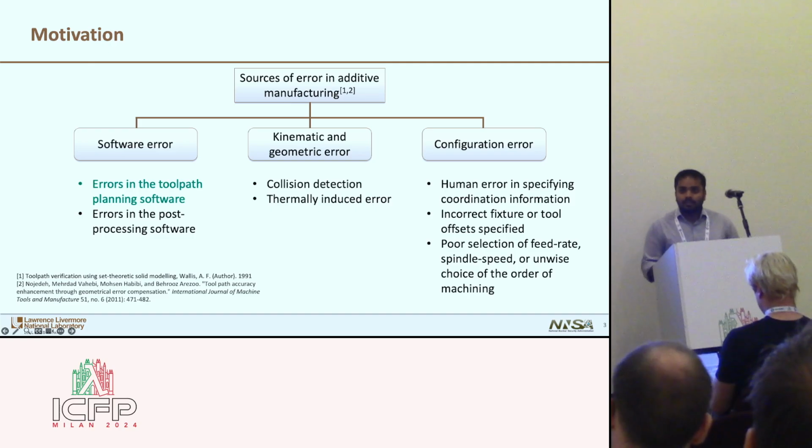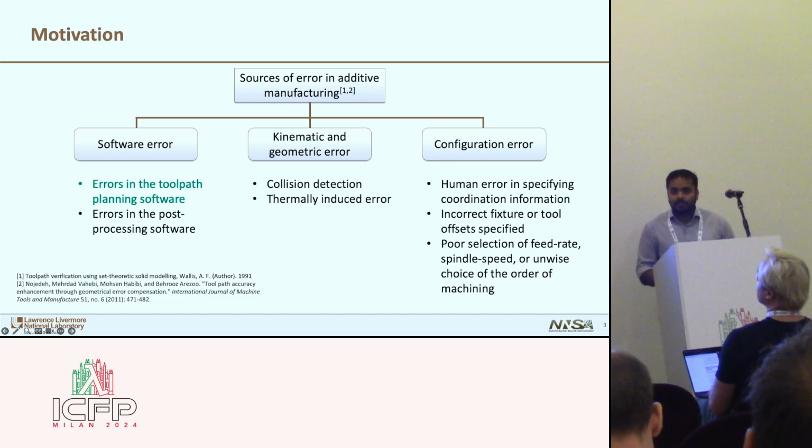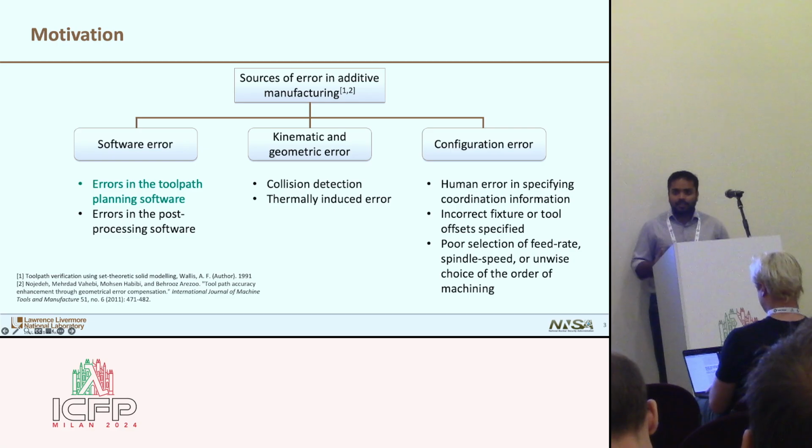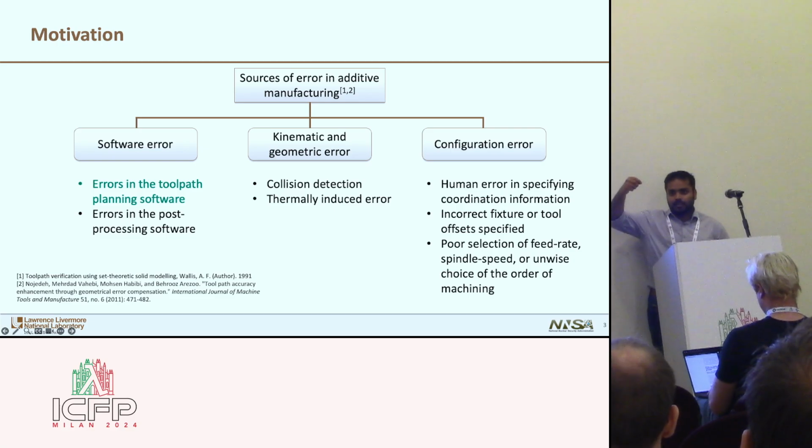Can I just ask a quick question? I didn't quite catch you mentioned extrusion. Oh, sorry. Yeah. So extrusion is basically the technique wherein filament is deposited, it's a fused deposition printing. So a filament is extruded from a nozzle, and then you heat the filament and melt it, and then you deposit it in a pattern which is specified by the CAD model. So yeah, material is extruded, and then you heat it.